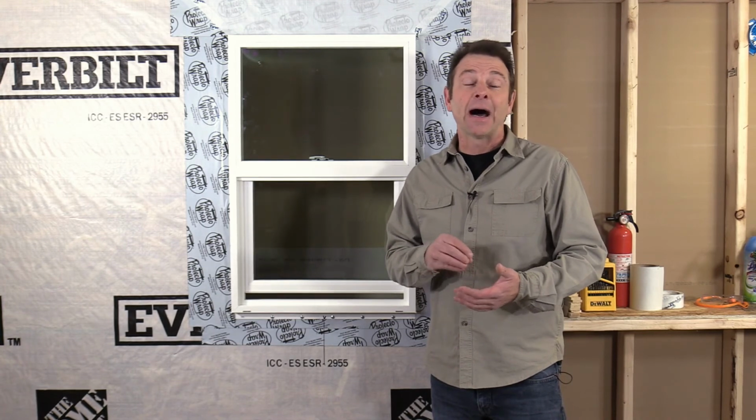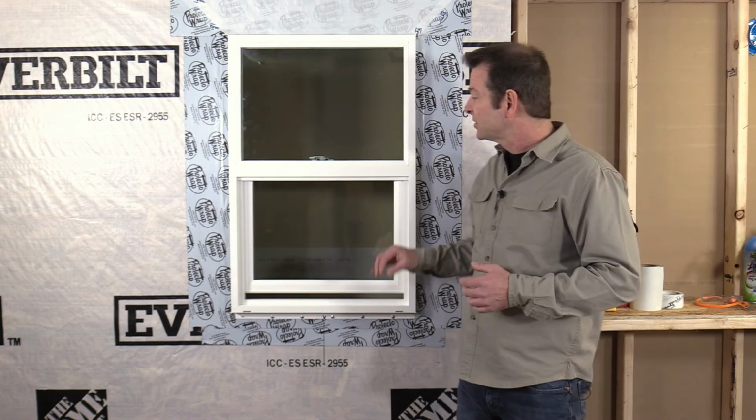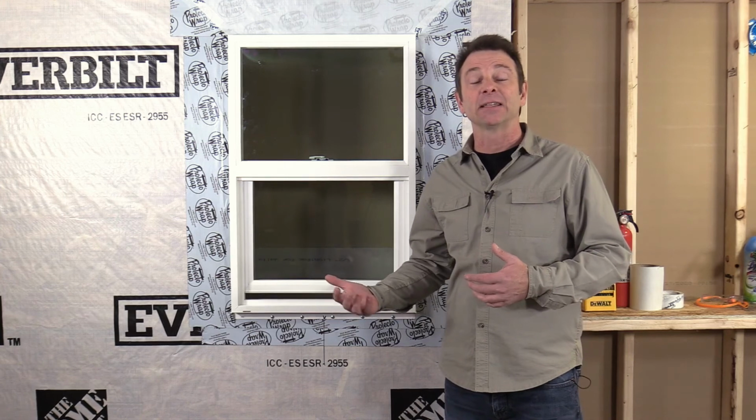Make sure that the product used is not a high pressure foam or a latex foam. This can cause undue pressure on the frame of the window. It can cause warpage and problems with that window working. And one thing to consider is this might not happen or might not be done by the window installation crew. It could be done when the house is insulated on the inside, but it's very important that it happens in the process to create that energy efficient, leak-free window.